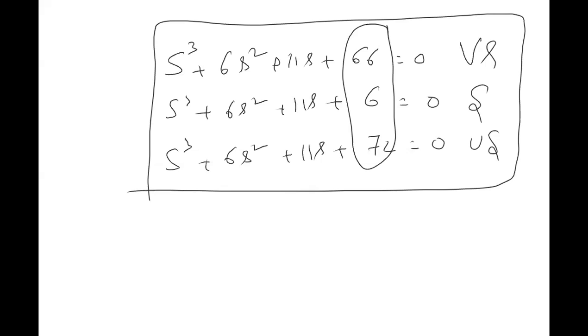If one of the coefficients in the characteristic equation is negative, then the system is unstable. Have you heard this rule? Yes. But I want to show you here, even if all the coefficients are positive, then the system can be unstable. Clear? So don't follow the rules blindly.